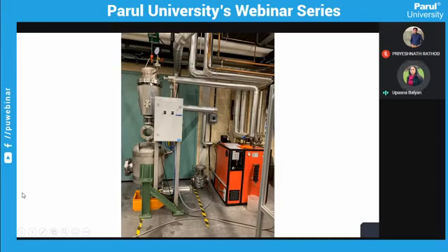And after that, this is the valve through which you can turn it on, and steam will travel to the chamber. This is the pressure gauge. You can see the pressure, and here I put 7 bar pressure for 20 minutes. It is a predefined time which we got from the literature. Obviously, every scientist will follow the path of another one, so we can rely on the literature.